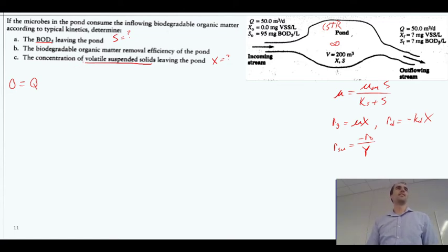Yeah. So we're going to relate it that way. Well, we're finding out BOD, so it can't be X plus anyway. That would make it equal 0. Right. So there's a challenge here, right? Because as we're starting to think about it, what do we do our mass balance on when it depends on both X and S? X depends on how much substrate there is, and substrate's what we want to find, right? So the point is that this is tricky.